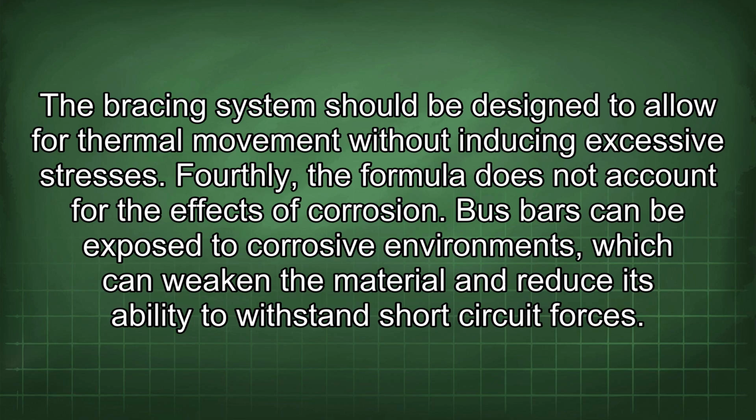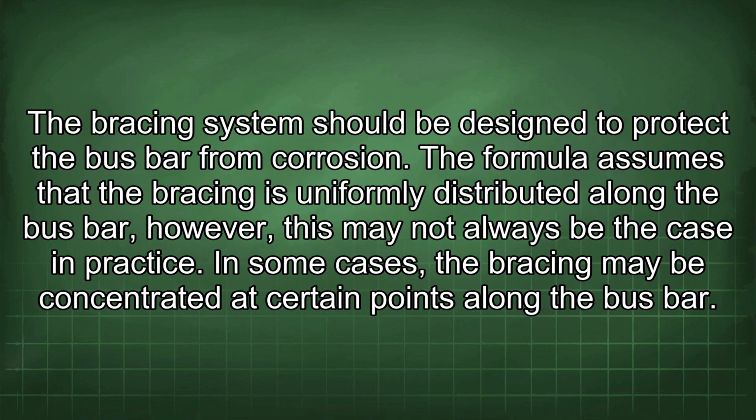Fourthly, the formula does not account for the effects of corrosion. Busbars can be exposed to corrosive environments, which can weaken the material and reduce its ability to withstand short-circuit forces. The bracing system should be designed to protect the busbar from corrosion.